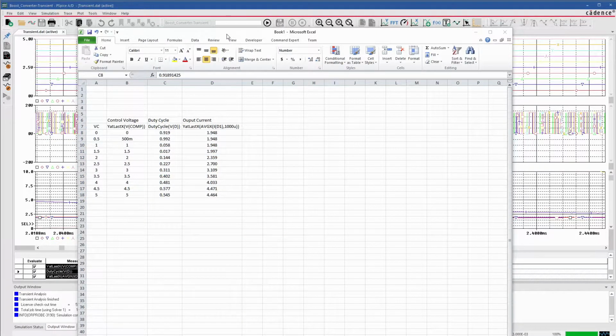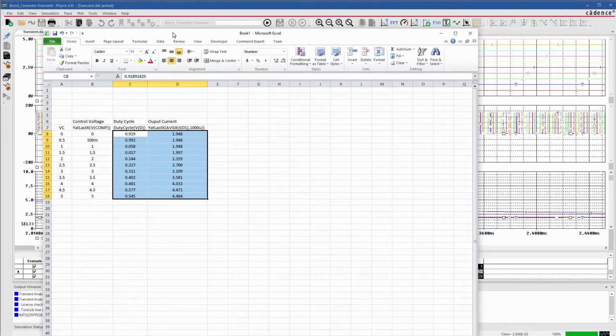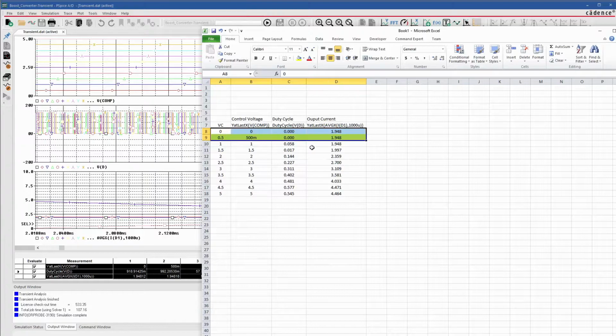These first two didn't really work because, well, it says milli here on these guys, but that's definitely incorrect because 0 is not a full duty cycle. So I think if we make these two 0, that's a little better. This point here is probably pretty inaccurate. This probably really makes sense because it has a little offset voltage before it actually starts switching. So it's probably below 1 volt. It doesn't really switch much anyway.